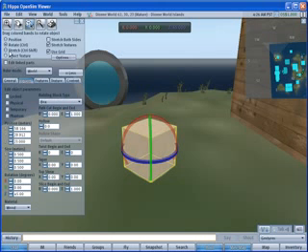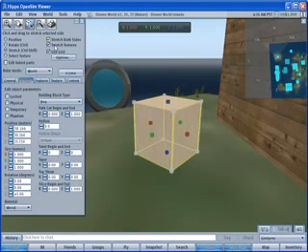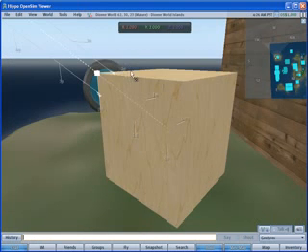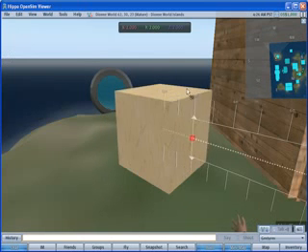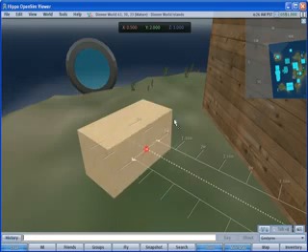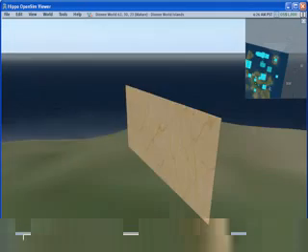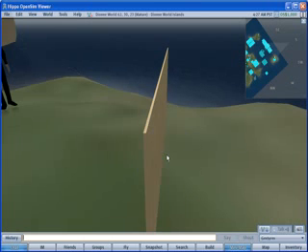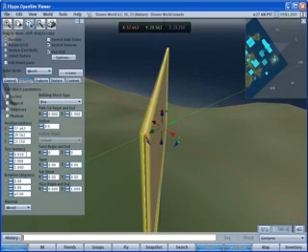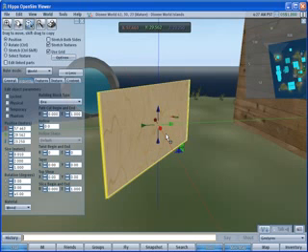Position and size are similar, so let's enter stretch mode. See that I have stretch both sides disabled, but by default it's enabled, so you will do like that. Like that. Okay, now let's demonstrate what stretch both sides can do. See that? We now have a flat, well, almost flat, but the minimum size for any axis is 1 centimeter, I guess. This, of course, can be worked around using prim torture methods, but those are outside the scope of this basic tutorial.